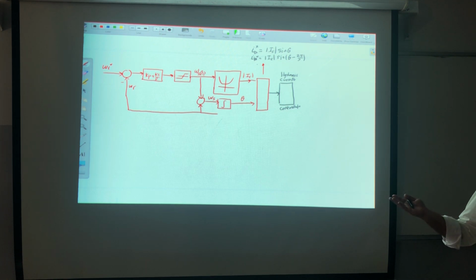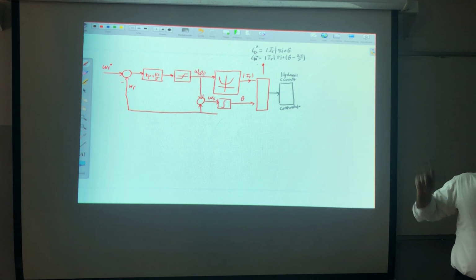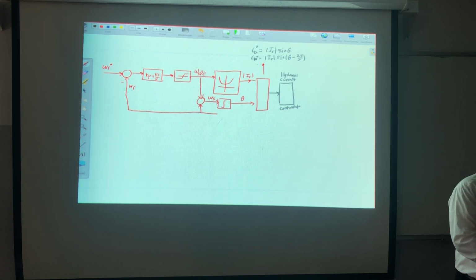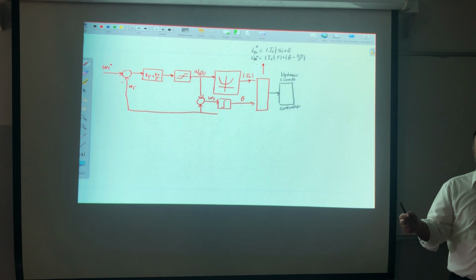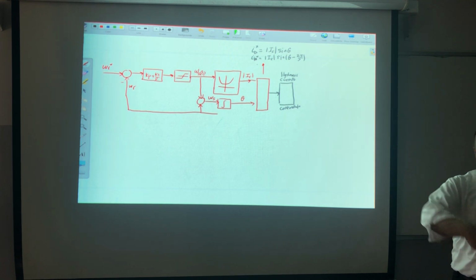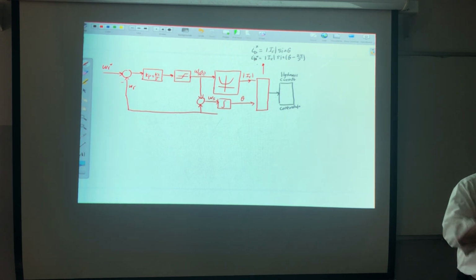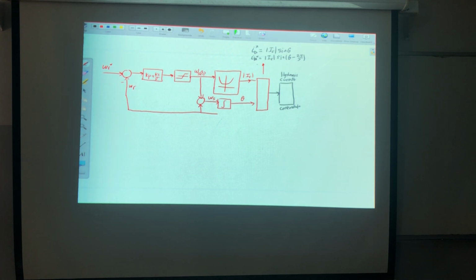It's a sinusoidal signal. It must be a sinusoidal signal. So simply this means that I will do hysteresis current control. And for the hysteresis current control, go 3 steps back to the DC drive and refer to the lecture when we discussed the hysteresis current control implementation.